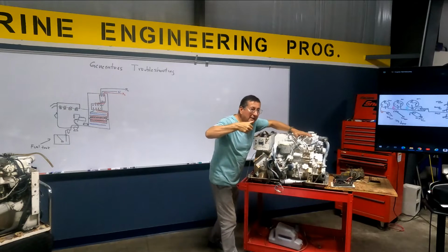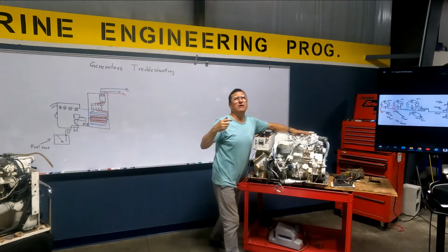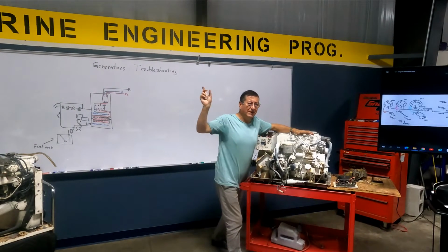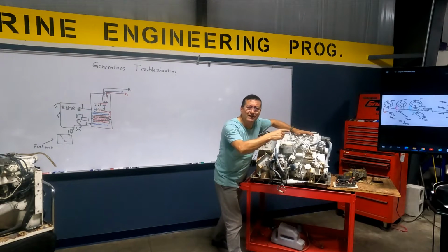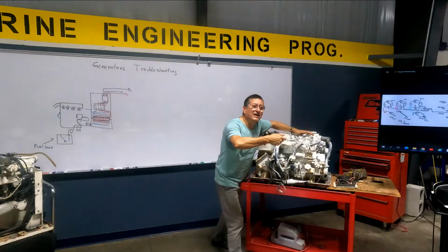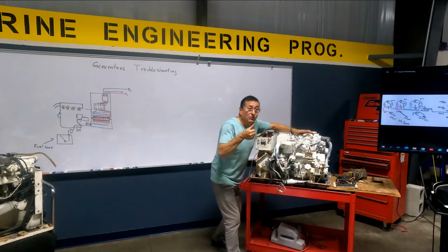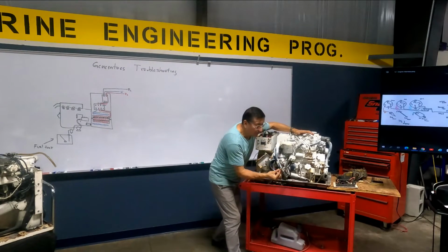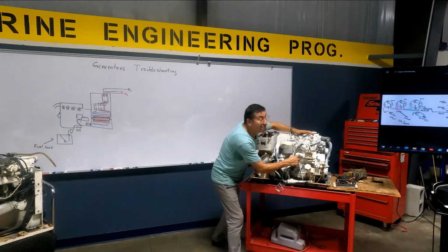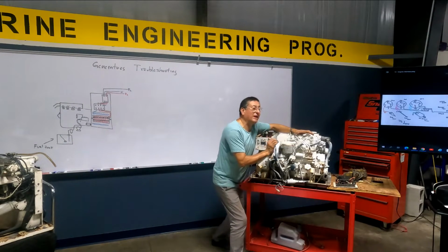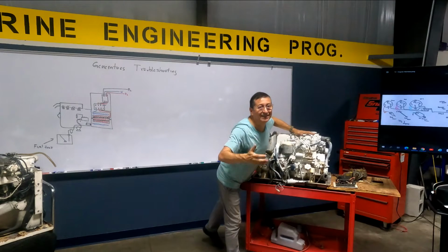You remember when you preheat? When you preheat, you bring power to the crank relay. You remember that picture? The crank relay allows the current to enter the start motor and the engine cranks. And additionally, when you preheat, you supply power to this transfer pump. You bring the fuel, and you supply power so the solenoid opens, and the fuel enters, and the engine starts.